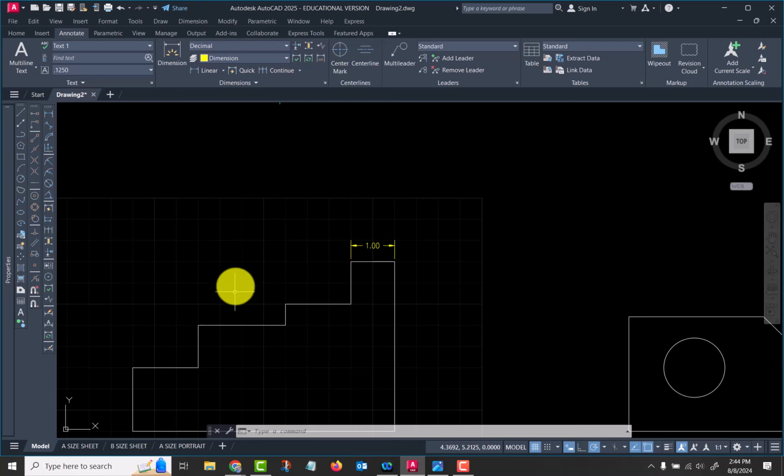Okay. All right. So that's those things. And it works the same way vertically. It all works the same way. If I were dimensioning this thing, all of these vertical dimensions I would place over here on the left side. That way the lines are not coming across the object. Okay. All right.